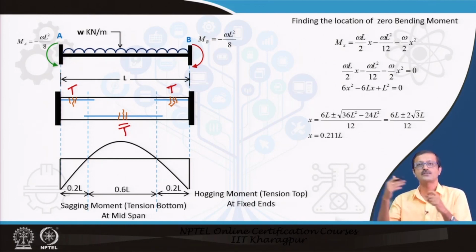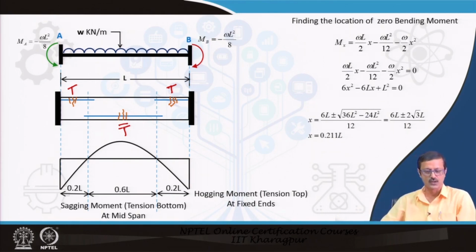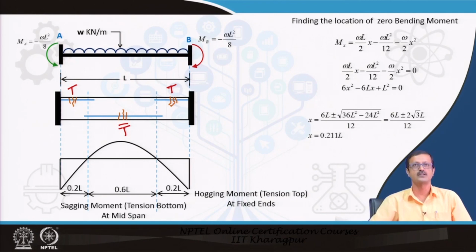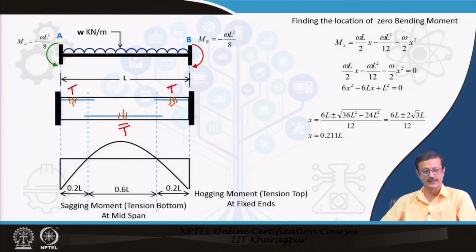So, the reinforcement has to be placed there, and we have to design for that. We have to calculate how much reinforcement is required. We have to stitch those cracks perpendicular to the crack. We have to put the reinforcement in such a way that it also takes the tensile stress. That is why it is important to find out the amount of bending moment, and where it will actually be occurring, hogging or sagging. Then from that point of view we can give the reinforcement properly, right.